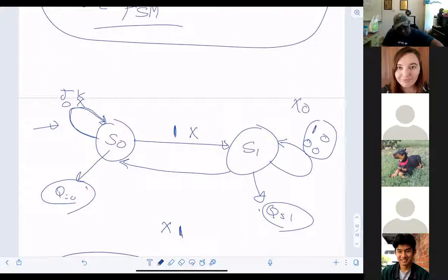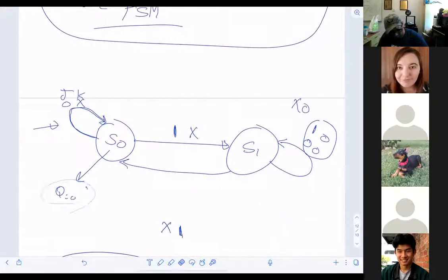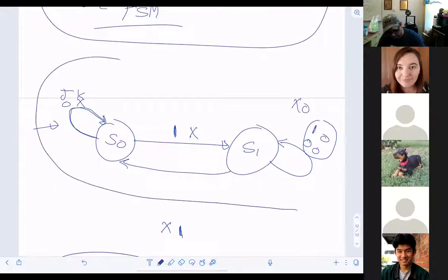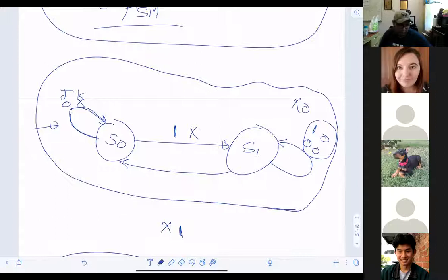You don't actually need to put this like this, this is useless. This is just for representing to you, but the thing in front of you now is the finite state machine using Mealy representing the JK characteristic table. Any question?